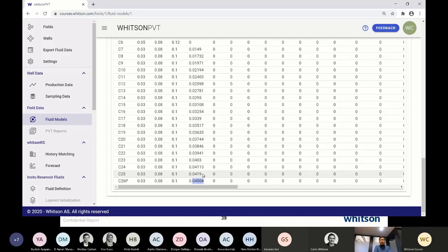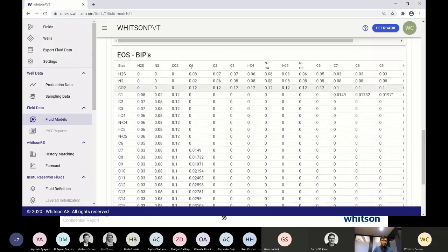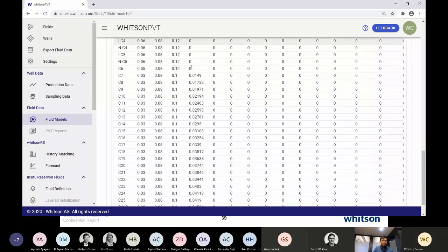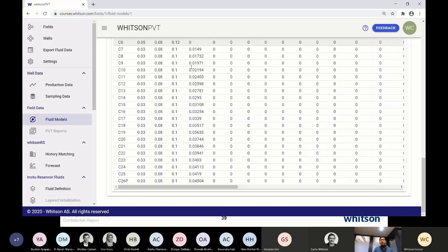And the other comment that these numbers have to be zero, like for the SRK equation of state model, which PVT sim characterization generally has. So we have a good exercise on this at the end of this session today, and we will see why you should not have exactly zero binary interaction parameters even for the SRK equation of state model. And as Curtis said, the binary interaction parameters for SRK may be smaller in magnitude compared to Peng-Robinson, for example, for methane and C7 plus fractions, but still you need some small correction there.